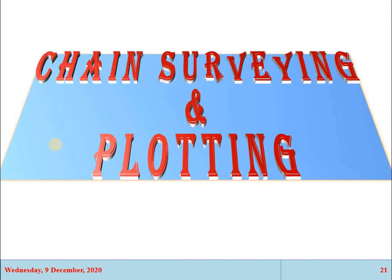If you have to survey an area which is comparatively small, for example the ground is fairly level, the area is open, and the detail which is required to be surveyed is simple and less, then chain survey will be suitable in that case.